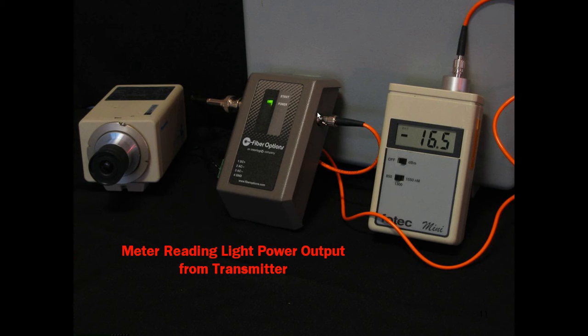And the receiver will have a spec sheet that says this receiver must see from -15 to -20 dBm of light power. If that amount of light power is reaching the receiver, then you know the receiver is getting enough light. So what's defective? The receiver's defective because it's getting enough light, but it's not working properly.